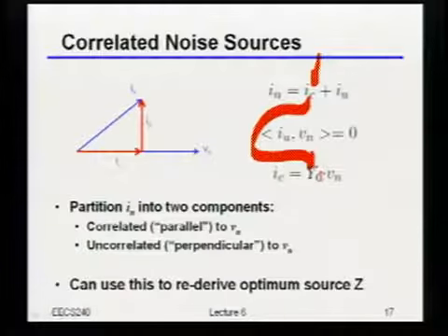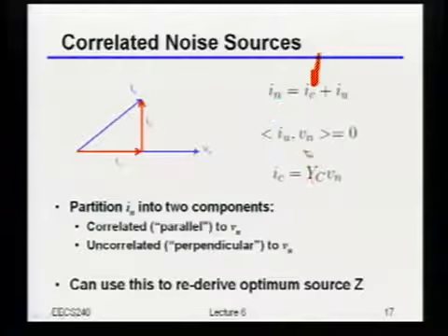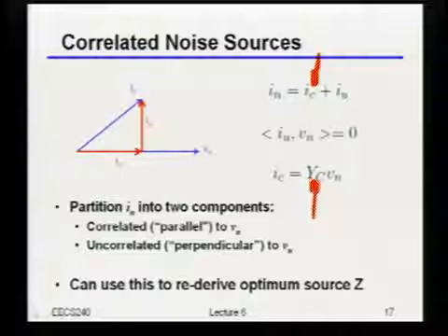It just tells you how the input referred noise current gets related to the noise voltage, okay? Now, I'm using admittance here because this could be a complex number at any given frequency, because the correlation could be coming through an inductor or a capacitor or something like that.